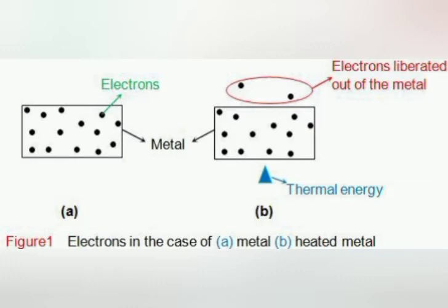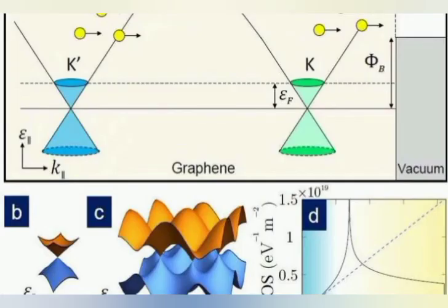The cathode ray oscilloscope consists of the following components: the electron gun with control grid, the deflecting plates, and a fluorescent screen. The electron gun consists of an electron source, which is an electrically heated cathode that ejects electrons. The electron gun also has an electrode called the grid G for controlling the flow of electrons in the beam. The grid is connected to a negative potential.